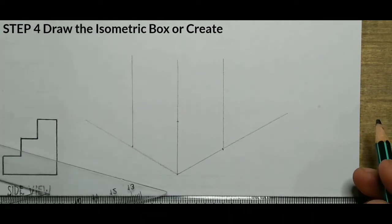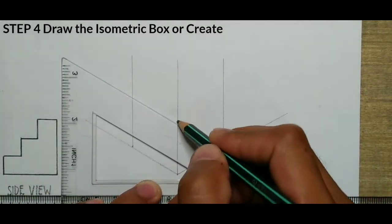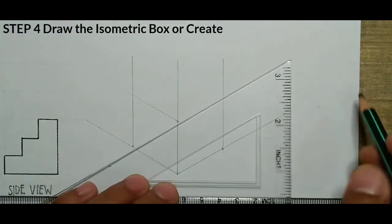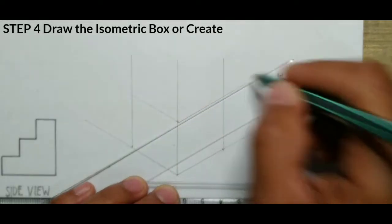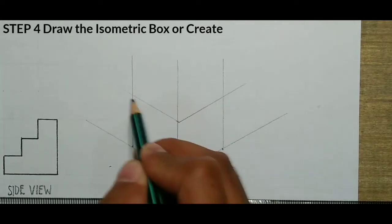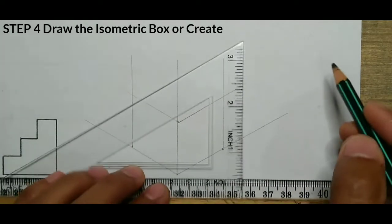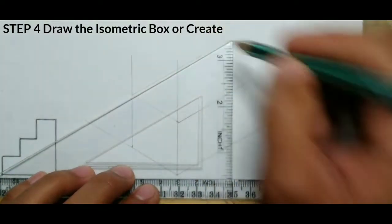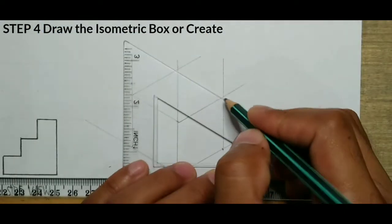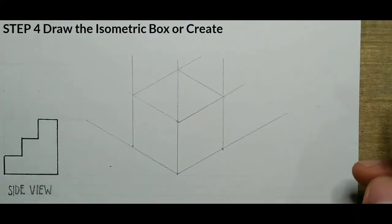Then, on this point, you project 30 degrees left and 30 degrees right. From these intersections, you project again 30 degrees right and 30 degrees going left to form an isometric box.